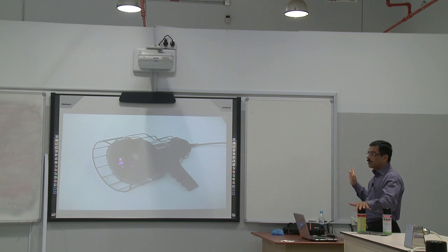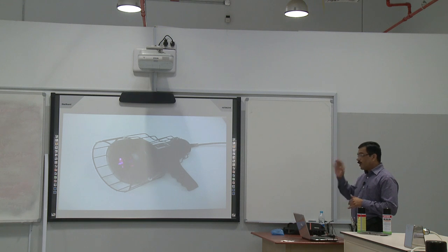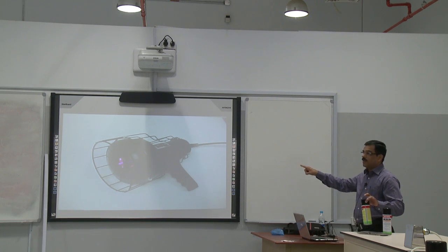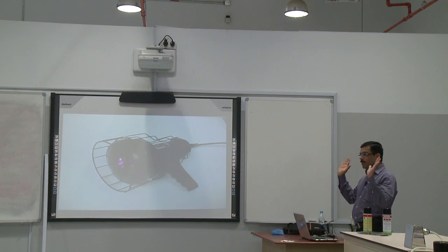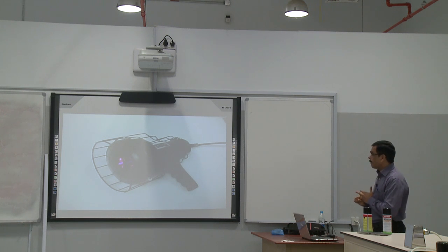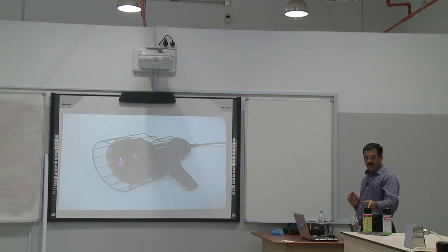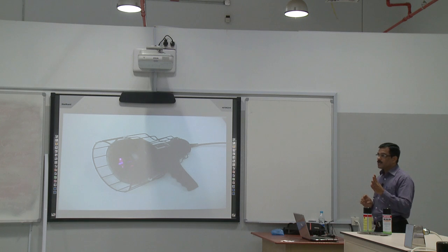So we don't have type 1 here. If we want type 1, we can purchase the type 1 penetrant with a UV lamp, ultraviolet lamp, and the area should be dark. In such an area we can use type 1. So we have only type 2 method C. Method C means solvent removable and a dye penetrant, and a developer, that is non-aqueous developer. These are the 3 chemicals we have.